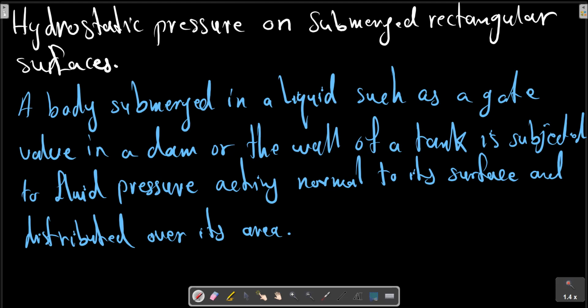In problems where fluid forces are appreciable, we must determine the resultant force due to the distribution of pressure on the surface, the force and the position at which its resultant acts. For systems open to the atmosphere, the atmospheric pressure P0 acts over all surfaces and does yield a zero resultant. In such cases, we need to consider only the gauge pressure, which is the increment above the atmospheric pressure.